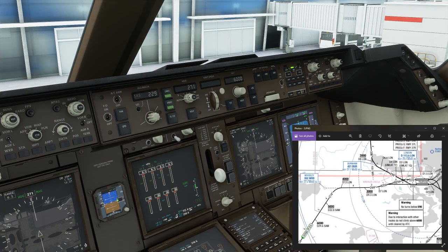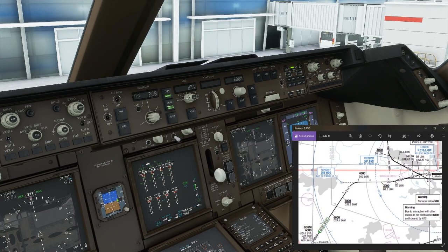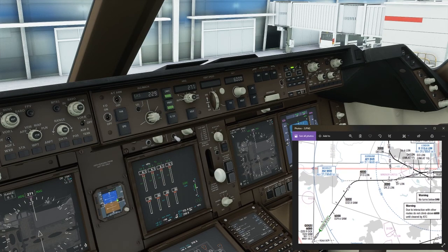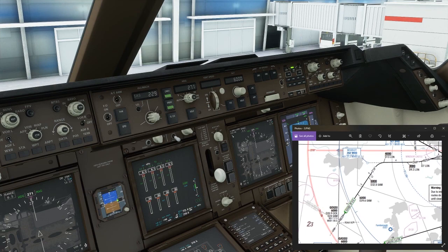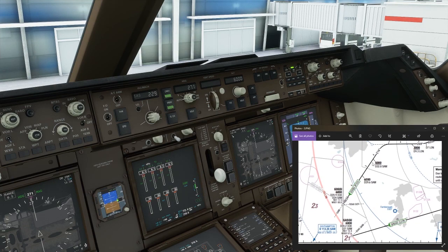Then it goes on the 256 radial from the London VOR. So it's the 256 radial, and it would be 256 that you'd be tracking, the direction that you're heading as well, out to 7 miles, and then you're turning right onto a heading of 269 to intercept the 269 radial to Woodley, and we'll do some NDB tracking whenever actually everything works. You need to be 3,000 feet at 9.3 miles from London. You need to be 4,000 feet or above, which is the line underneath it, at 13 miles, and then you're turning left again onto 214 degrees to intercept the